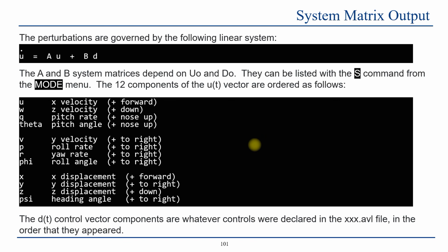So this should be everything that we needed to cover, and this should be putting all the information that we had learned together to come up with a design, the mass distribution, and how we can use them to analyze the stability of our aircraft, how it's performing, its behavior, what we need to do to change certain aspects to make our aircraft more efficient, increase, for example, its E or Oswald efficiency factor, make sure that it doesn't stall, make sure that it's statically stable, and check its dynamic stability for various modes. So that is all for the review of the AVL.